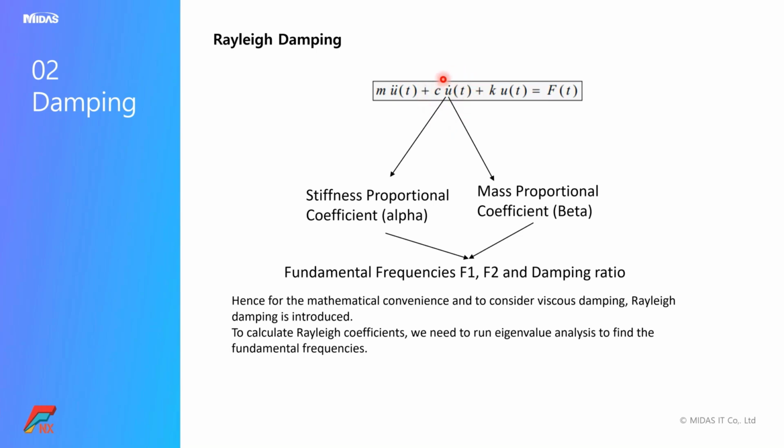So basically, an additional component has been developed. But due to the recent advancements in the studies, you can actually provide the damping behavior as a hysteresis behavior in the stiffness component itself. So what happens is, because of the hysteresis behavior, the stiffness will change with respect to time. Hence, this matrix will get updated with respect to time, and because of this, the damping will be applied inherently. So that's for hysteresis models. If you're not dealing with them, then it's better to apply it as a Rayleigh damping.